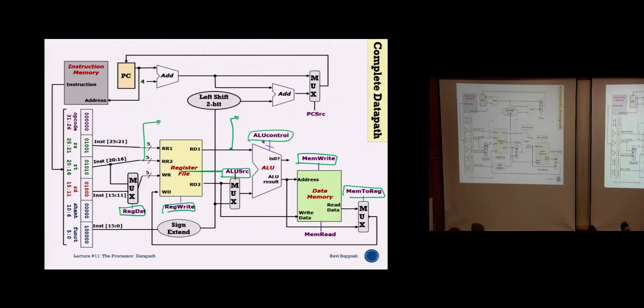What I'm saying now is, if instead of byte addressing, they're using 32-bit addressing, so you have 32-bit addresses, and each address has 32 bits instead of a byte. So you're saying it's a word address. That means each memory location is one word. Then I can't access a byte. You probably need to read the whole word, and then do your own handling in the code. Okay.